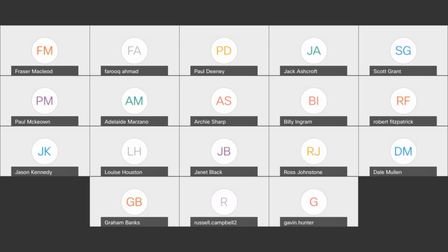So different designs for the fish plates, no common terminology, and no tolerances in the comments. If the drawings are not consistent, then of course you cannot expect the manufacture to be perfect or meeting the requirements.